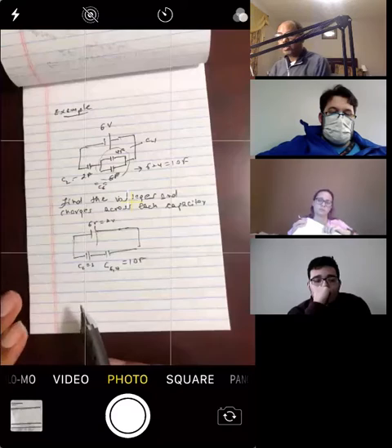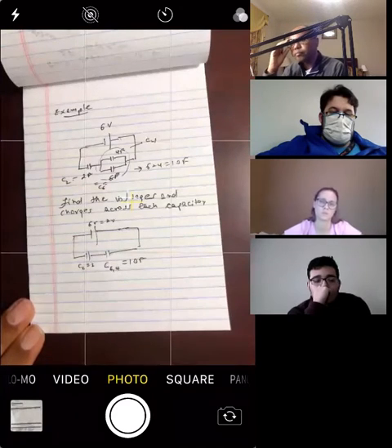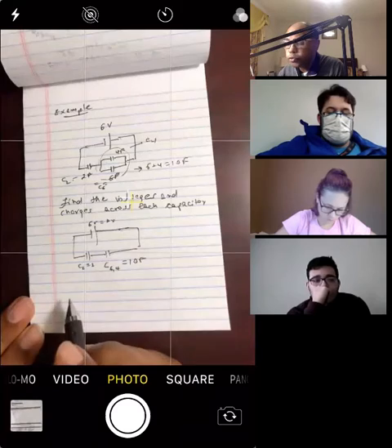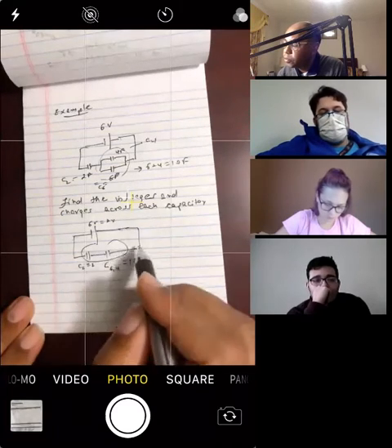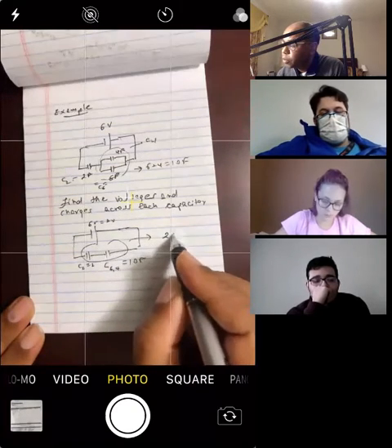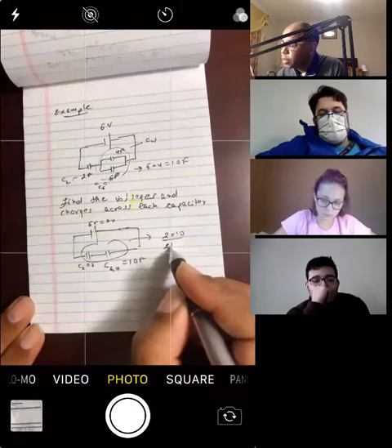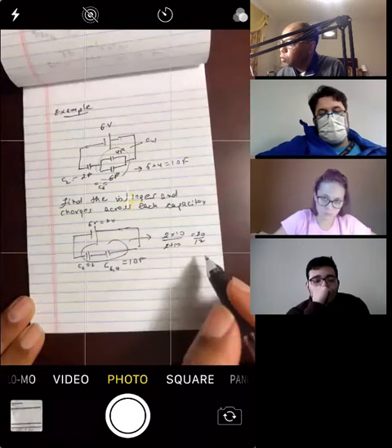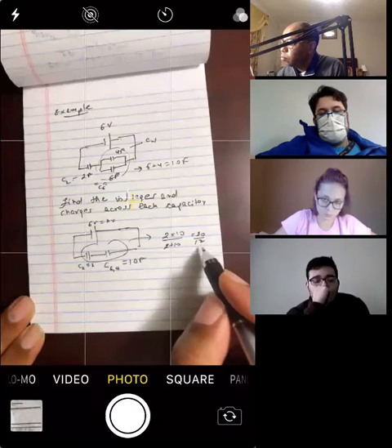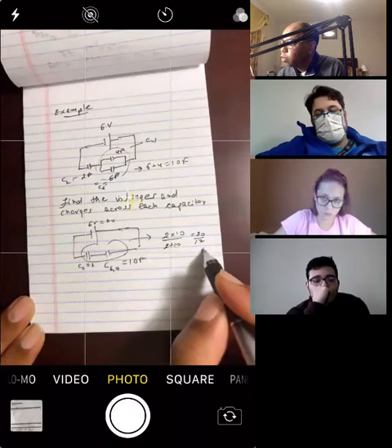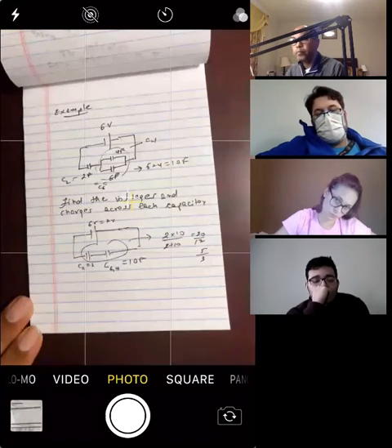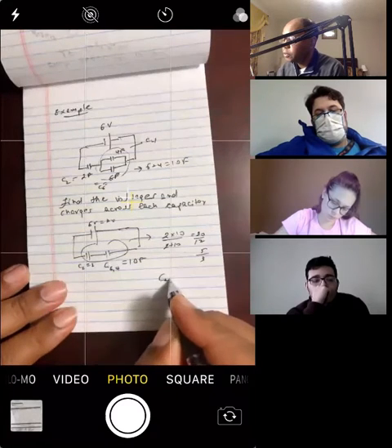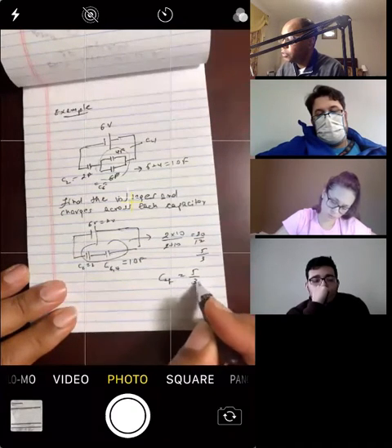We can further simplify it. We can replace it by a single capacitor, right? And these are in series, so it's going to be product over sum. Okay, so when I combine these two, it is product over sum. 2 times 10 divided by 2 plus 10. Okay, that is 20 over 12, or 5 over 3. The equivalent capacitance is 5/3 farad.